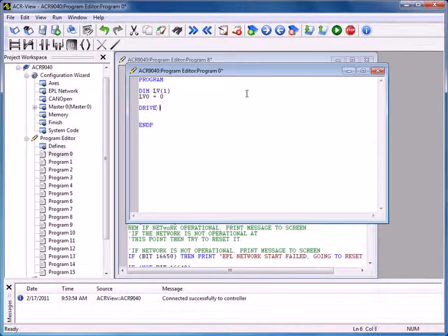I'm going to do simple relative moves. So for my first set of moves, I'm going to move both X and Y simultaneously. So I'm going to say X with a /, and I'm going to send it for a -10 revolutions, and Y for a -10 revolutions. Then I'm going to send them back in the positive direction for a relative move.